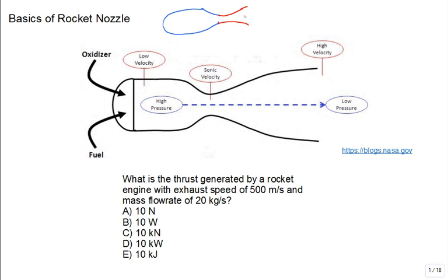And so now what do we have? Well, let's talk a little bit about a rocket. We have an oxidizer and we have some fuel. And you put them together and great things happen. You have a fireball. It's high pressure, high temperature, right? And now this high pressure is needed, and this is the converging section. That's our traditional nozzle. Things are going to speed up.